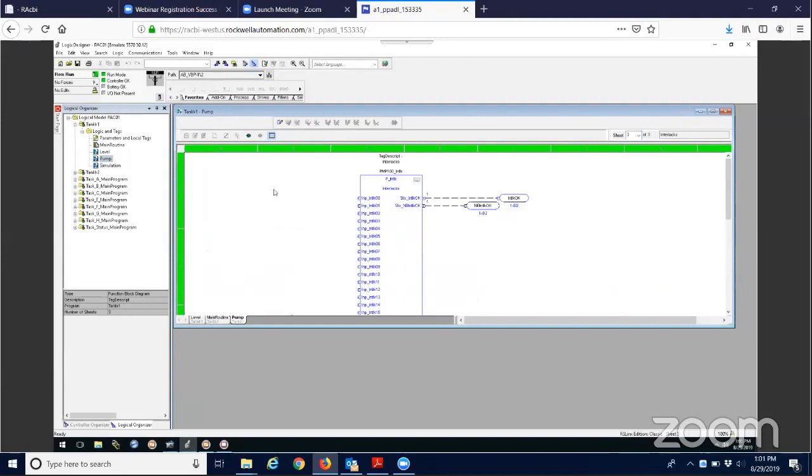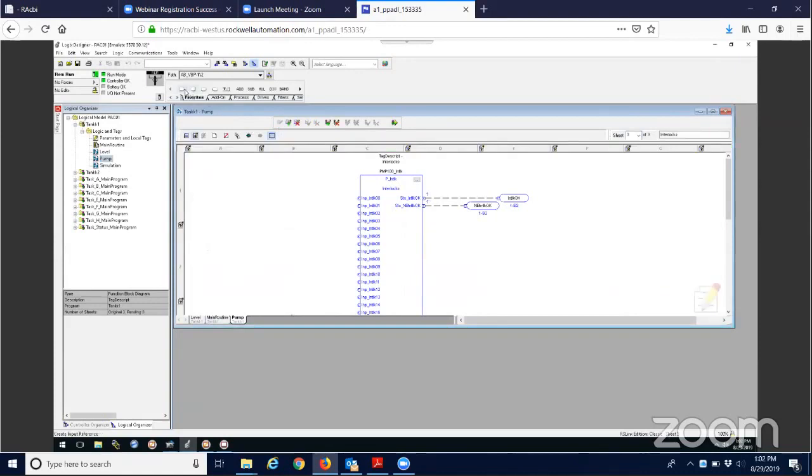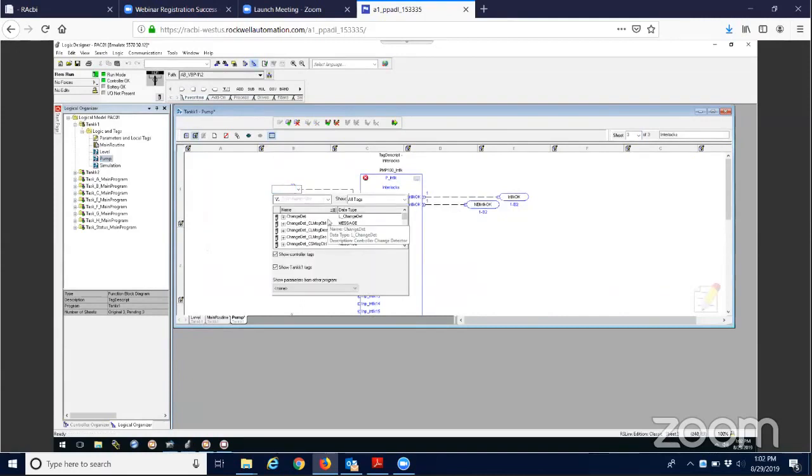But for a DCS guy, this is what he's going to want to do. So how do I do this? I'm going to start a pending edit and pull this down. This is an input screen, so I'm going to just link these up. I know from my little cheat sheet that I need LT100's low status, so I'm going to find LT100 here.